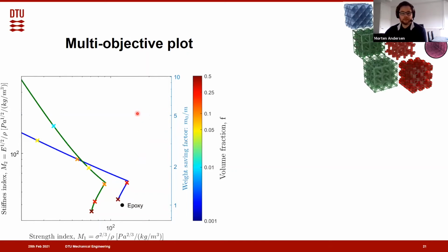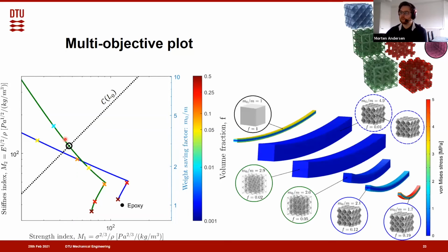And then we get back to this coupling line here. This line couples the geometric constraints on the problem. So whichever microstructure is crossing this line at the highest point is the optimal one. That means here that this specific beam problem prefers to have this isotropic truss lattice.